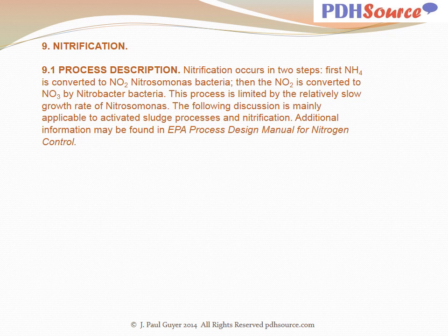The next advanced wastewater treatment process that we will look at is for nitrification. Nitrification occurs in 2 steps. First, ammonium is converted to NO2. Then the NO2 is converted to NO3. Both of these are bacterial processes. This process is limited by the relatively slow growth rate of Nitrosomonas.